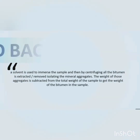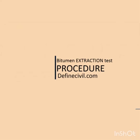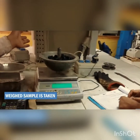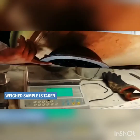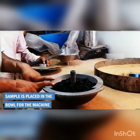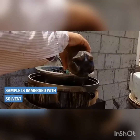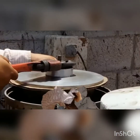Now, let's have a look at the procedure to be followed for the test. The sample taken is weighed to the nearest of 0.05% of its mass and is recorded as W1. It is then placed in the bowl for the extraction machine. The sample is then immersed or covered with the solvent. That can be petrol of about 5 liters, or it is better to add commercial grade trichloroethylene or benzene and let the mixture stand for about an hour. The purpose of solvent is to disintegrate the test portion.